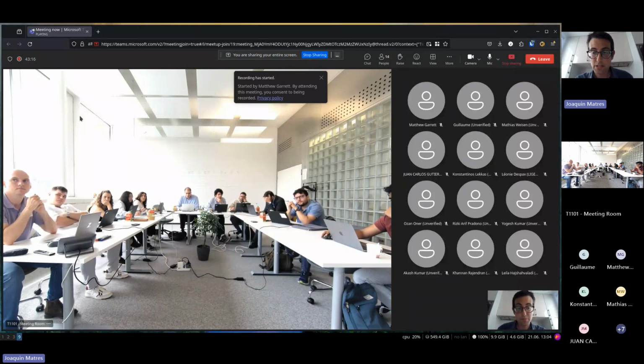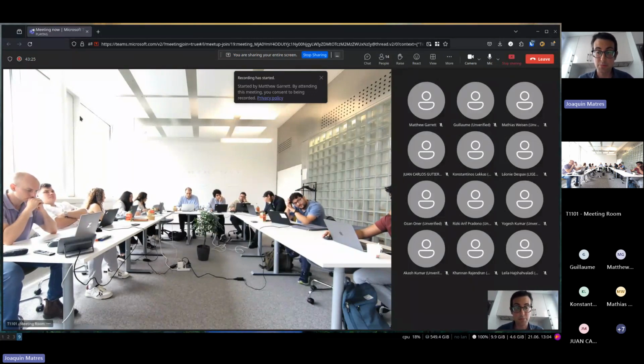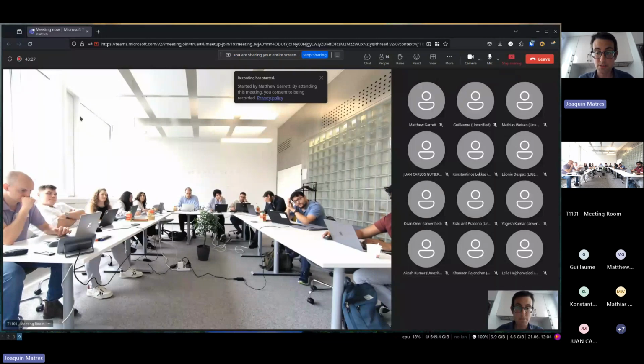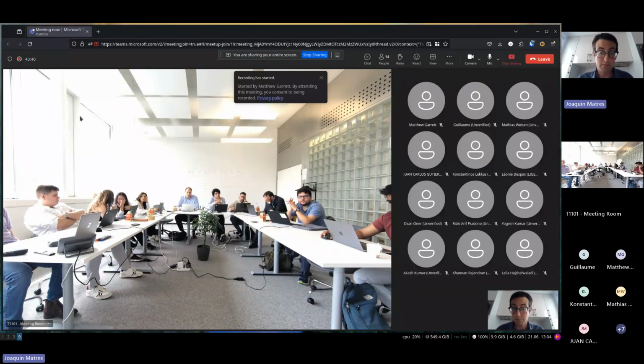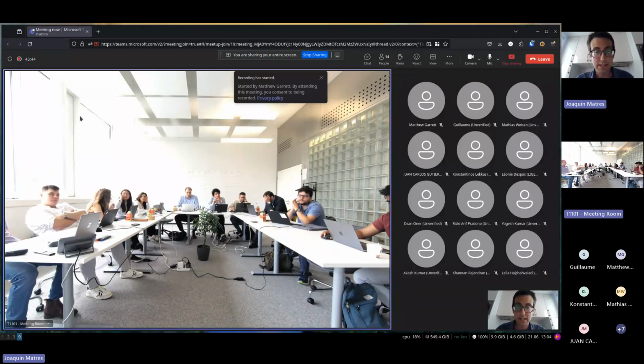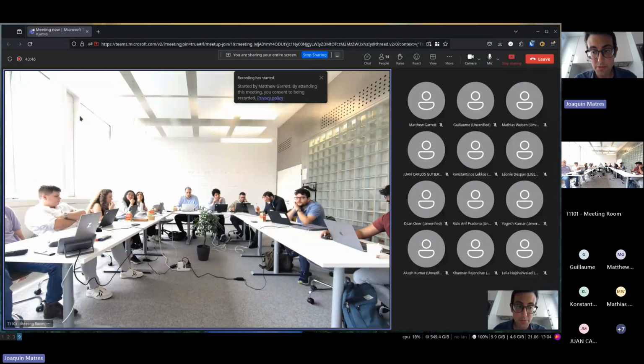But if you build your own DRC deck in Klayout, you have to make sure that as the foundry changes the process, the DRC deck stays up with the process. So that's also something that as a user, as a designer, you are paying money to the foundry, so you should be the one asking for this. And if the foundry gets a lot of requests like yours, if a lot of people are asking for DRC layout decks, they will put effort. But it's only a handful of foundries that are supported at the moment.